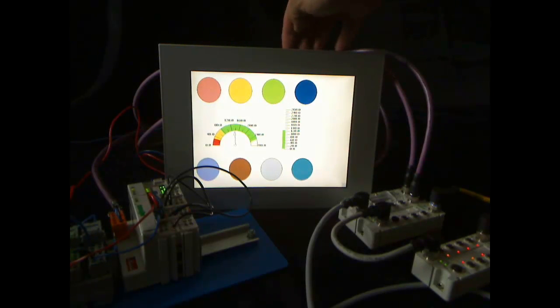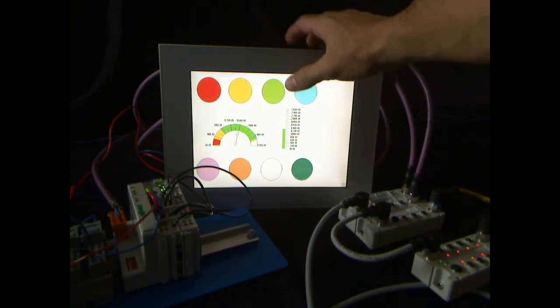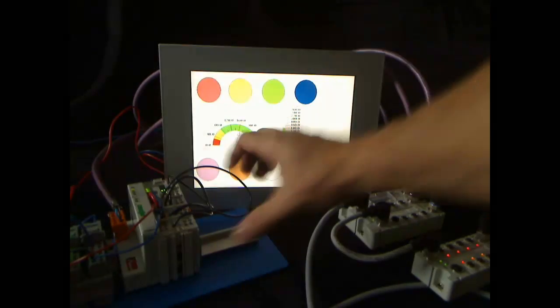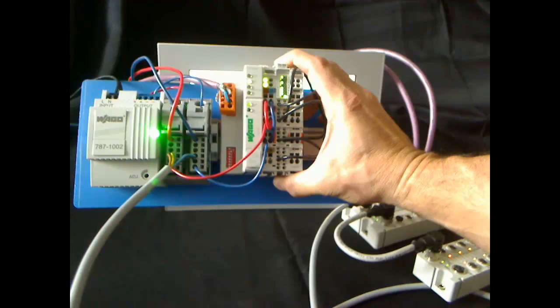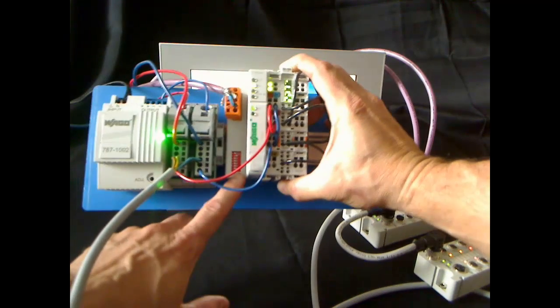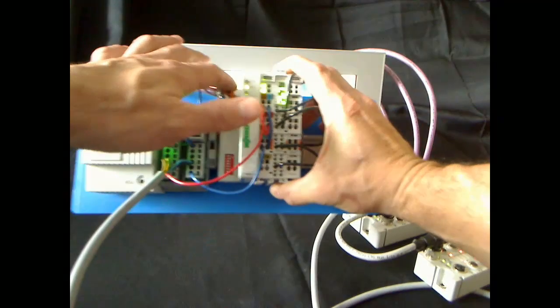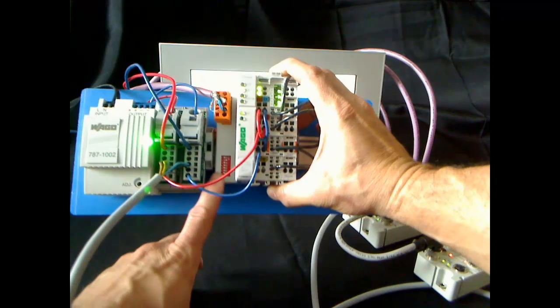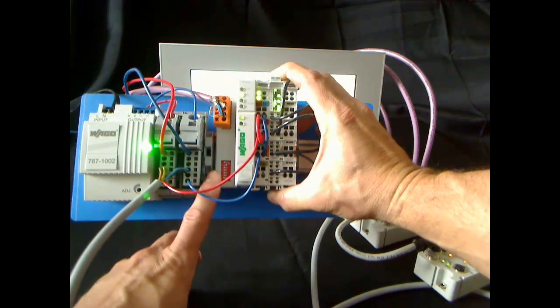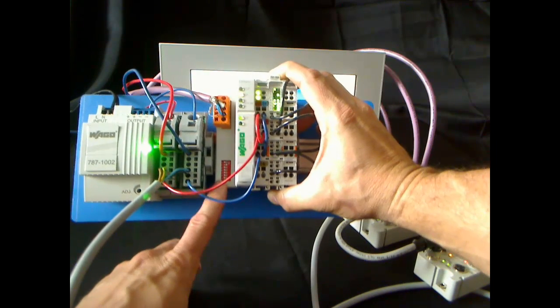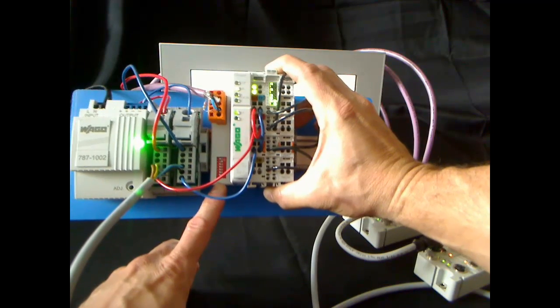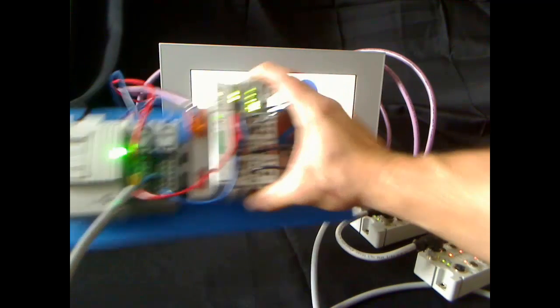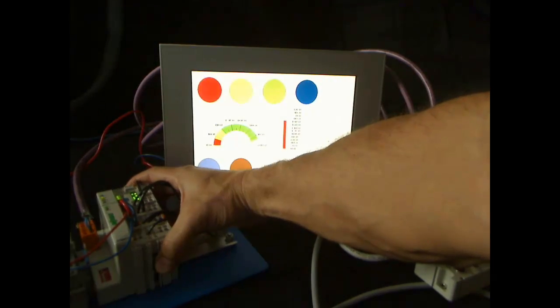Now you can see the WAGO Perspecto CP TV panel running the actual executable code here. We have our WAGO IP20 node, where you can see we have dip switches on the front and the CANopen connectivity. With the dip switches, we set the baud rate and node ID itself. And of course we have full setup and configuration documentation on these. Just wanted to point out how easy it is to set up the baud rate